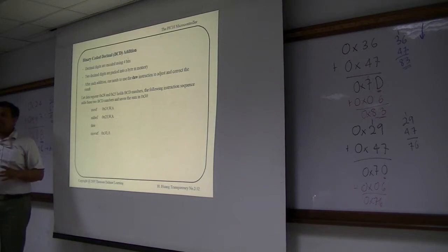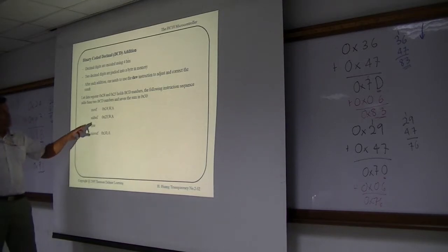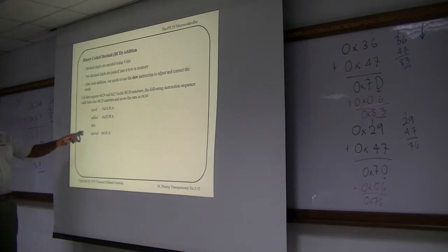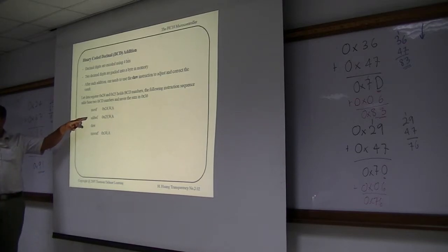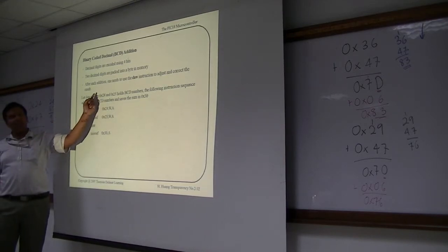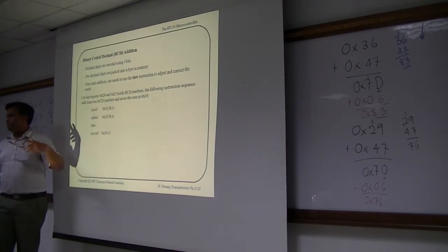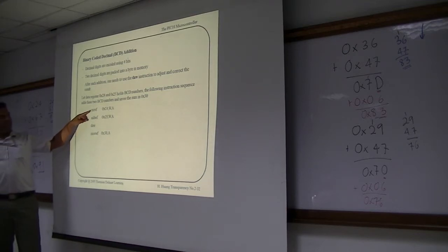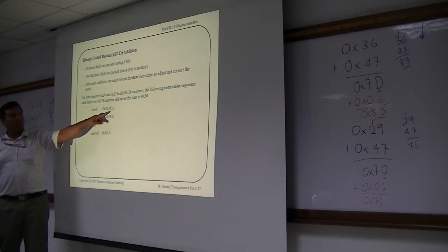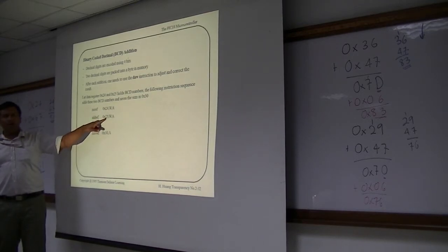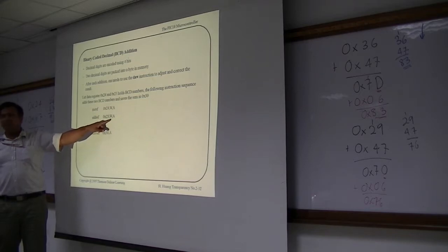So the same steps: you move hex 24 to the working register. Can you all imagine this? Hex 24 plus 25, store the answer at hex 30. Simple, same thing. But there's one additional thing here. So you move the content of hex 24 to the working register, and then you add the content of the working register to hex 25, you'll have the answer, right?